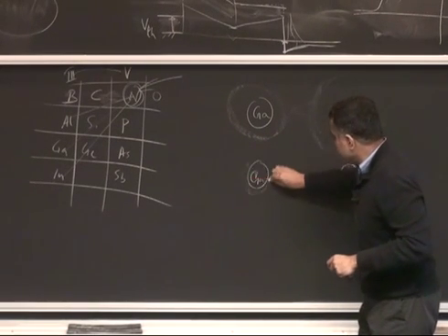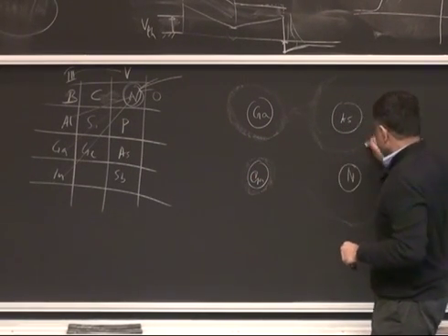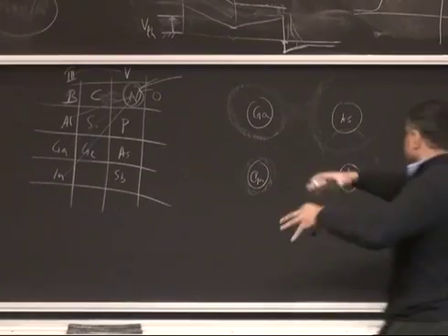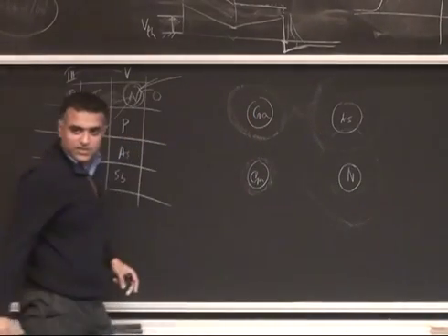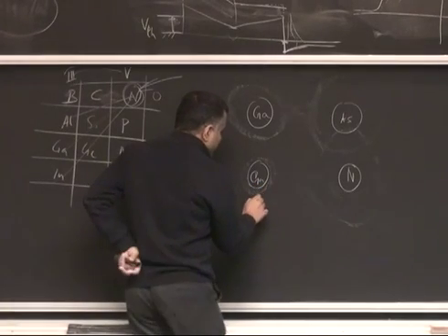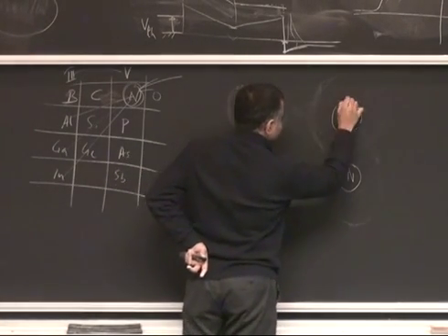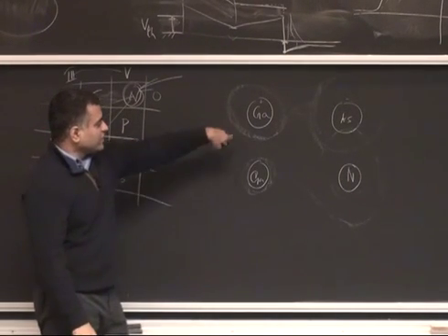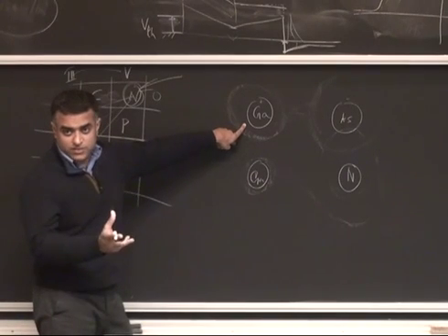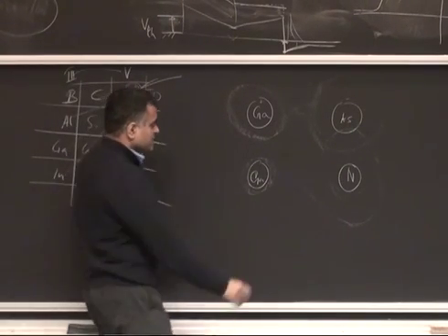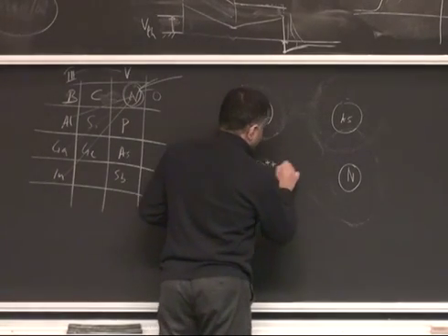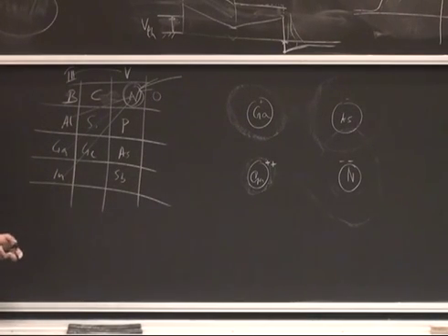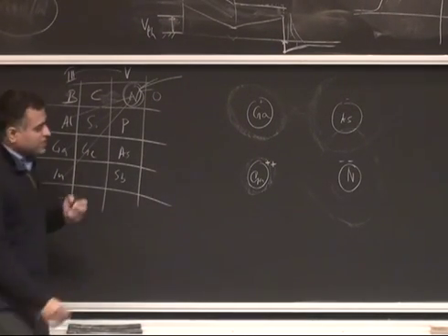But this thing is very polar, meaning nitrogen basically sucks out the entire electron cloud towards itself. The electron charge cloud is mostly near nitrogen. So if you look at it from a point charge perspective, this is slightly positive charge, this slightly negatively charged, so there's a dipole. Every compound semiconductor has a little dipole in the bond. It's a covalent bond, but there is a slight amount of ionicity to it because of the difference of electronegativities, and that thing is amplified a great deal here. This bond is very unequal. It's not really an ionic solid, but at the verge, it becomes very ionic, so very polar.